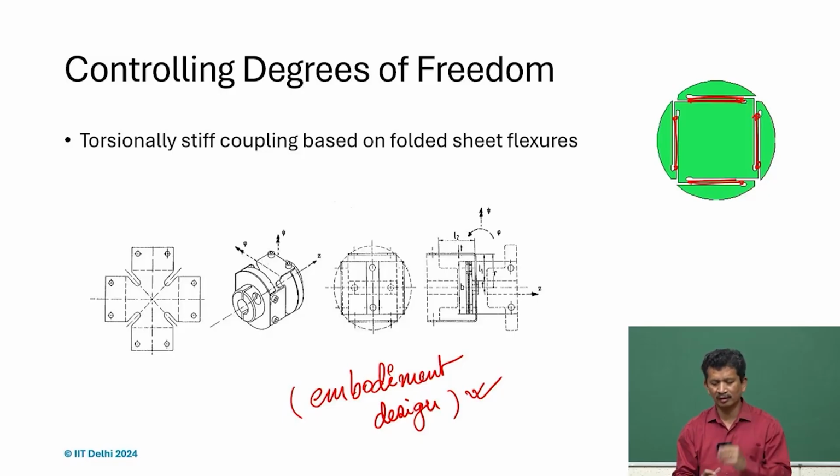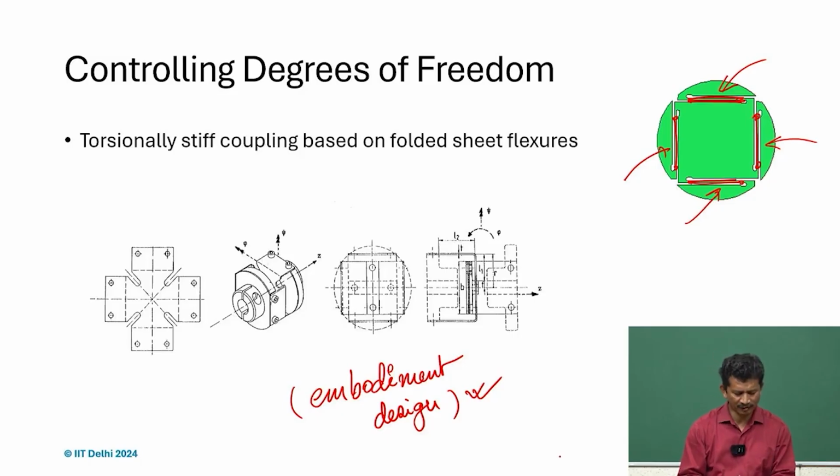Out of this big thing, that tiny part is the functional element, which provides the required constraints, but at the same time also provides that flexibility, and that is how you release the 5 DOF, which if we constrain, then it will be over constrained, and we may have to give some tight tolerances in some of the things. So, be aware of that.